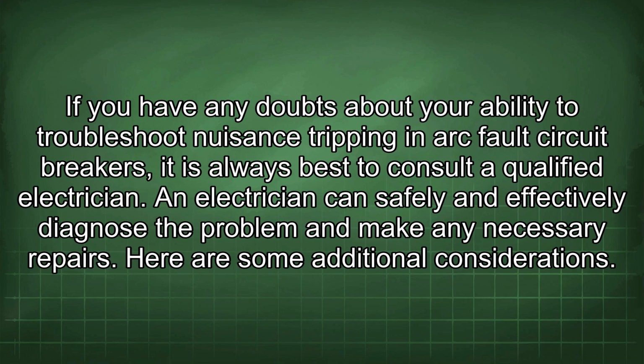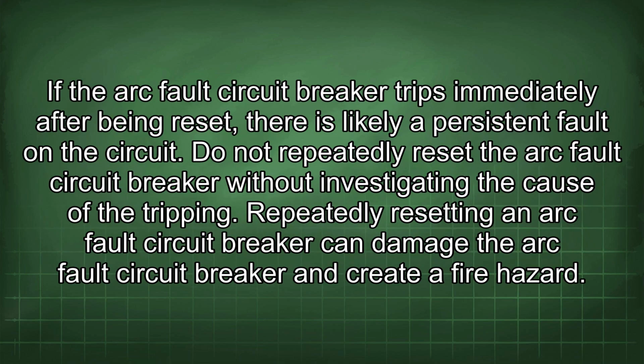Here are some additional considerations. If the arc fault circuit breaker trips immediately after being reset, there is likely a persistent fault in the circuit. Do not repeatedly reset the arc fault circuit breaker without investigating the cause of the tripping. Repeatedly resetting an arc fault circuit breaker can damage the breaker and create a fire hazard.